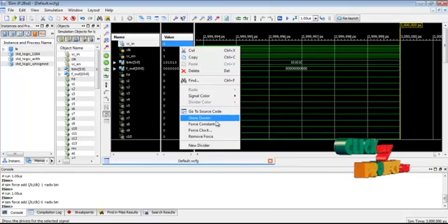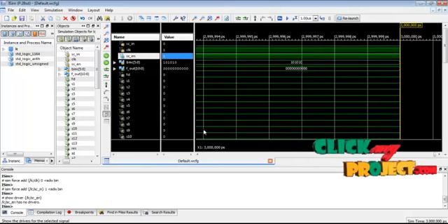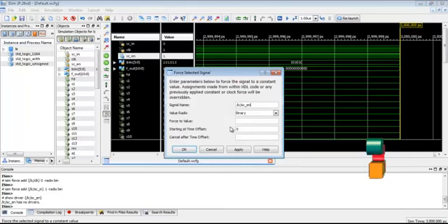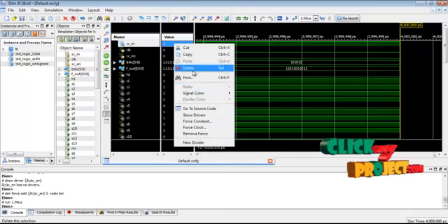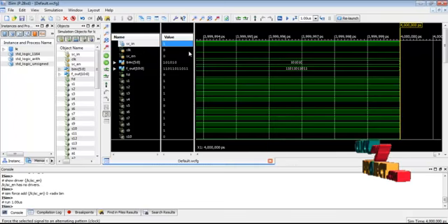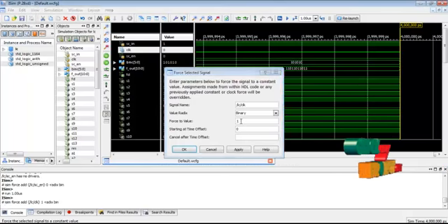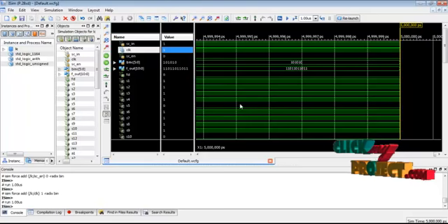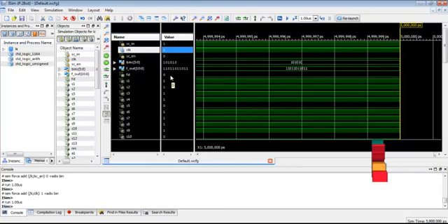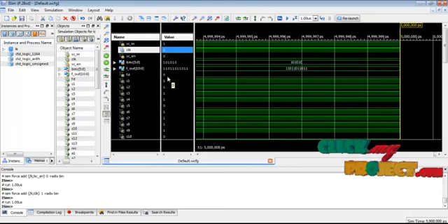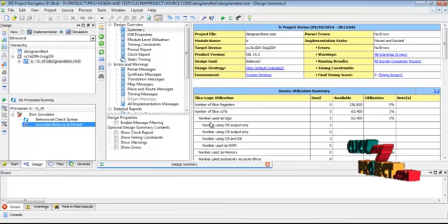Then we activate the scan input signal and deactivate the scan enable signal. We run the clock fully. Then we get the output test pattern results, and finally the fault detecting signal is 0 for the simulation result. We certify the testing architecture simulation result.